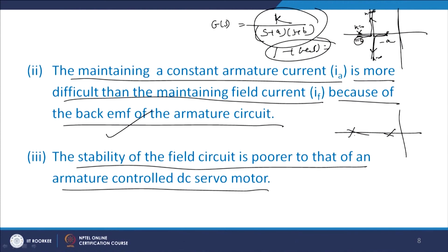So, we will find that for a second order system the root locus is like this. One root locus starts from here, this is a breakaway point, other is moving like this, other is moving like this, from the same breakaway point. You can see how to read root locus from any book, but for this point an explanation of root locus is important. So, here we will find that for a second order system, as we change k from 0 to infinity, the root locus always lies on the left hand side.